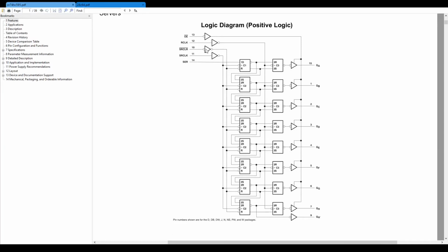What I said is this clear signal will only clear the shift registers. Then we have all zeros here on the outputs, but the output register will still contain whatever it did in the beginning. So we have to just pulse our clock here and then clock in the zeros. And finally we have then reset our shift registers.